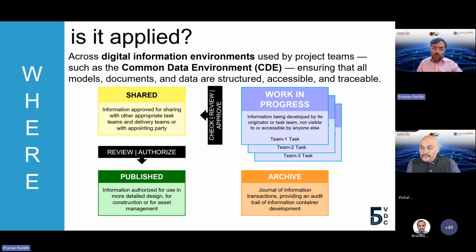And all of that gets coordinated and collaborated in the shared space. Once we all agree that this is good to be sent to site for actual execution, we again take it through a review and authorization process and submit it to the published area of the common data environment. And that is the area that is then available for the larger stakeholders, maybe the sub-vendors, the contractors, the site engineers, and they will only see the final outcome, the published data. And that is how the common data environment works.